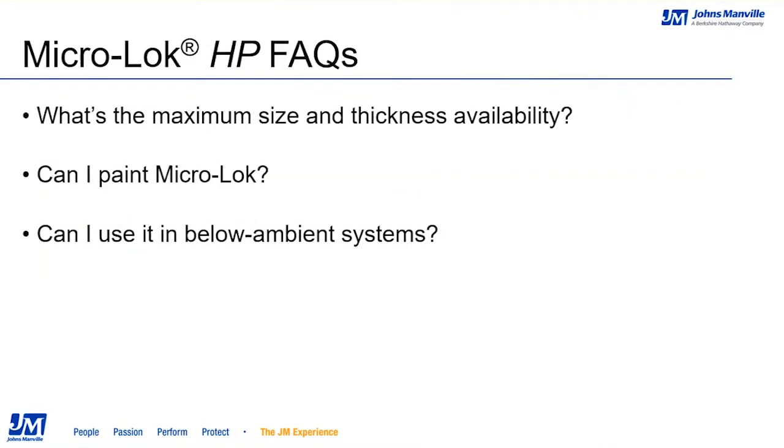We'll review another one of our offerings, Microflex, which can be used on even larger size pipes and tanks, in a few slides. Second question, can I paint Microlock? We do not recommend that our insulation is painted, as it voids the 25/50 flame smoke rating as well as the manufacturer's warranty. We test our products and know that they meet 25/50 requirements. So when anything is added, like paint, which could function as a fuel source, we can't guarantee that our product with the paint will continue to meet the rating.